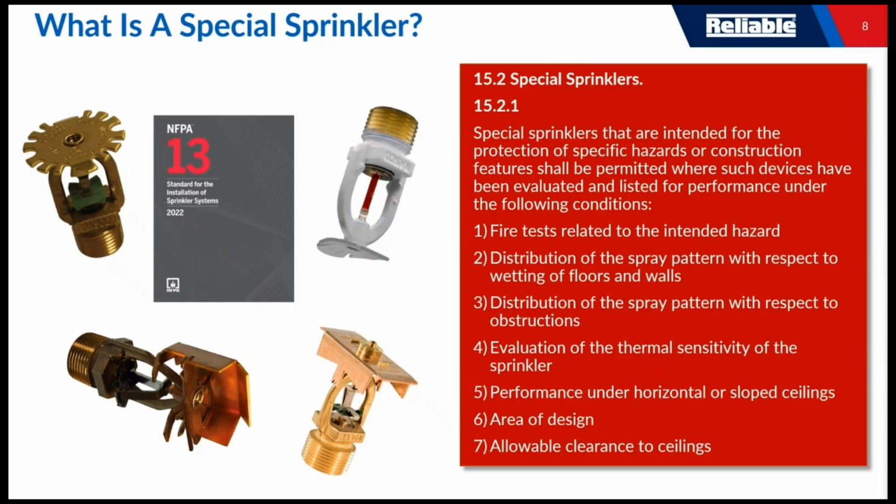Well, NFPA 13 actually provides us some guidance on how to create special sprinklers. Basically, if you opened up a copy of NFPA 13, it's going to vary upon which edition you look at, but they're going to tell you that you need to solve 7 problems before you can bring these products to market. First one is that you basically need some fire testing related to the intended hazard. Focus on distribution of the spray pattern with respect to the wetting of floors and walls, and distribution of the spray pattern with respect to obstructions.